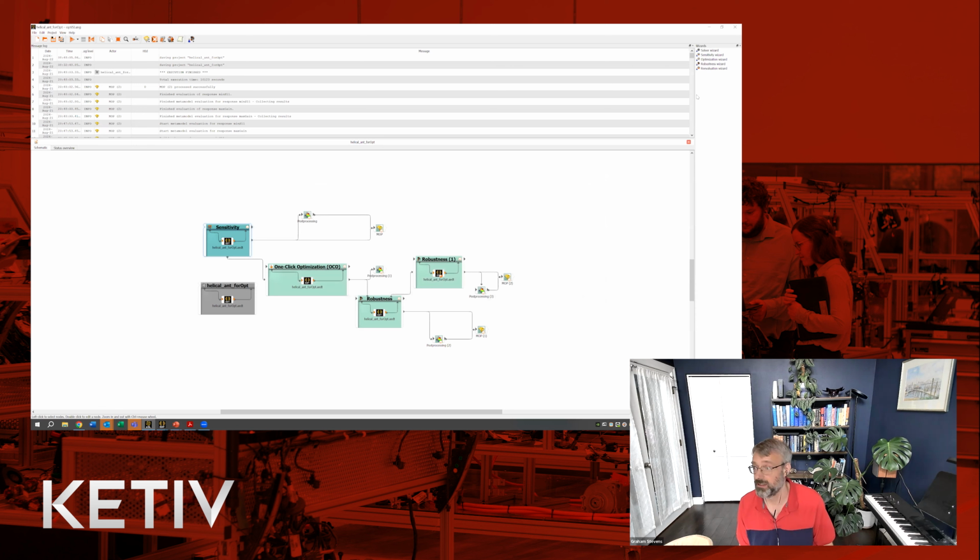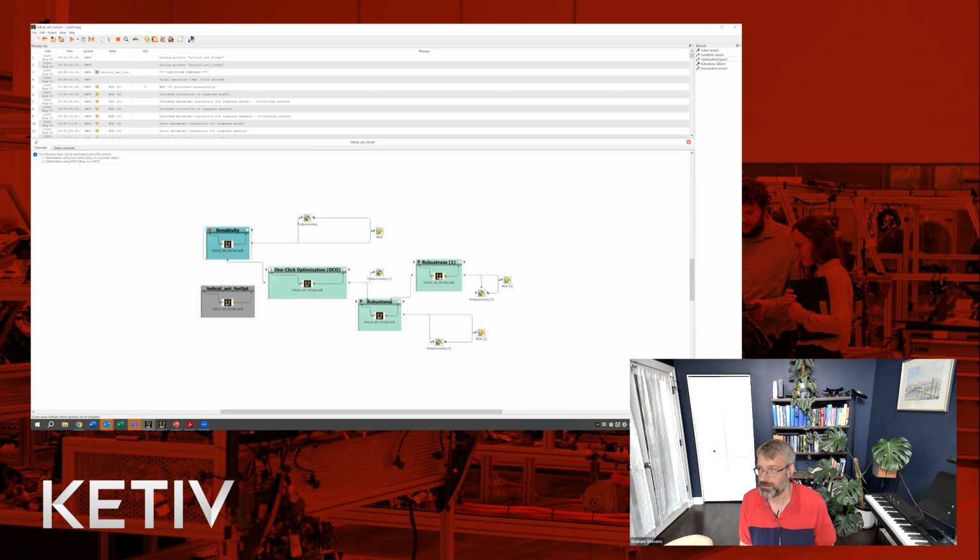And similarly, if we have an optimization, once we've identified which variables are important, and we say eliminate consideration of the variables that aren't important, we can then take this optimization wizard, drop it onto the sensitivity, so it uses the results of the sensitivity as the basis for the optimization, and we run an optimization analysis.